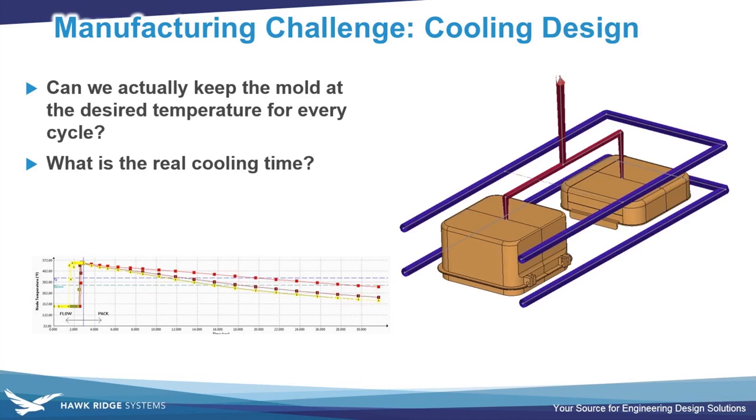In reality, no mold is going to have a uniform temperature. There are going to be hot spots in the mold and cool spots in the mold. And of course, one big challenge in mold design is adjusting the layout and the material of the mold, and most important of all, the cooling line layout, to try to reduce those hot spots and keep the mold at the right temperature. So this is something that we can now tackle in SOLIDWORKS Plastics Premium, the highest license of this tool.